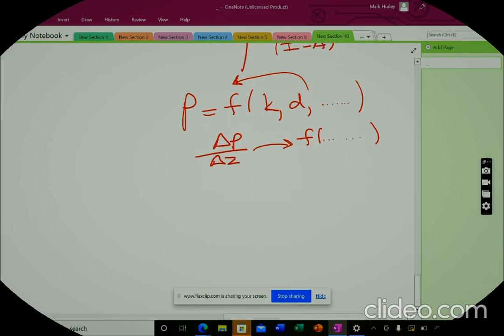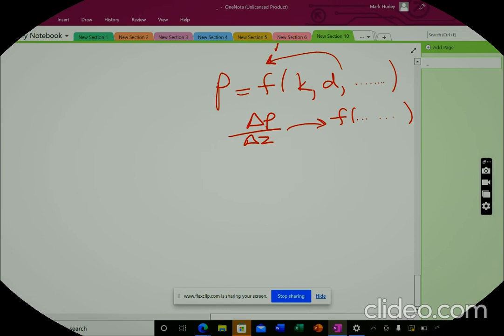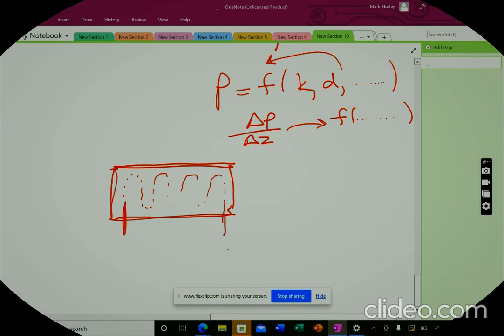Now, the last formula I'm going to mention was interesting because we were doing bridge de-icing. Imagine you have a bridge, and this is the surface, a bird's eye view. We have pipes at the underside of the slab. This is the inlet end, this is the outlet end. Of course, the inlet temperature is going to be greater than the outlet. This is the max, this is the minimum, and the minimum should be at the perimeter over here.